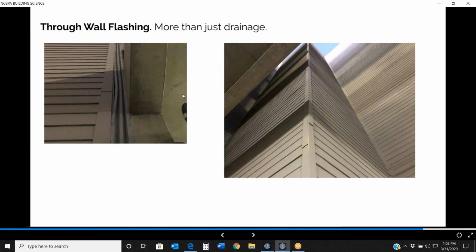A lot of times I'll get pushback on through-wall flashings at lap siding installations because we're not going to get as much movement in the lap siding. Sorry, let me back up for a second. With wood framed, you also need them for crush or shrinkage to help minimize the effects of that on your cladding and your fenestrations. And with lap siding, I get a lot of pushback: hey, it's lap siding, it's going to shrink as the building shrinks. We don't need a through-wall flashing.